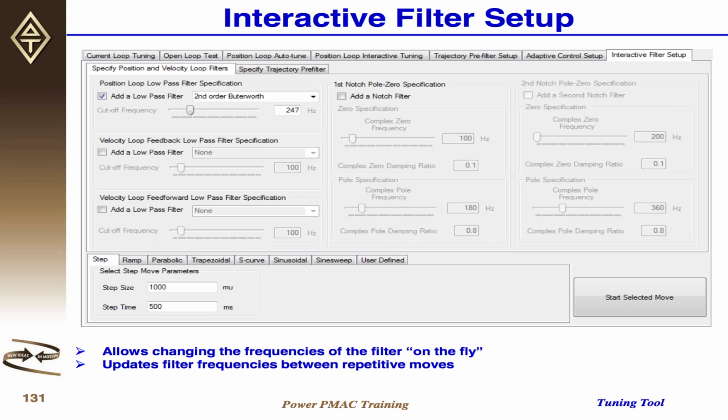Here's one thing to do. They can go to the filter calculator, put like 250 hertz, look at the noise, because as soon as you put the notch, you're going to see that noise is going to be eliminated, and do a move. And then come back and change it to 251, 252 to find the perfect spot. For those, they wanted something like this. So as soon as you change the dial and stop the mouse, it's going to directly implement on the fly the filter coefficients. So this way they can find the exact frequency in a really simple way.